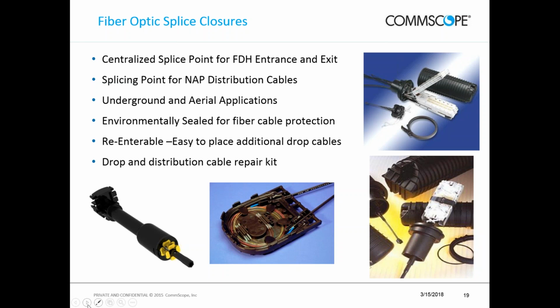Select a fiber closure that's easy to access again, because you may need to get in there again to add to the network. Also, you should be prepared to use drop cable and distribution cable repair kits, like this picture in the lower middle here. Nothing can protect against a properly motivated landscape project that went out of control, where you've got a customer that has dug up his drop cable. So always be prepared to have something like that on board.